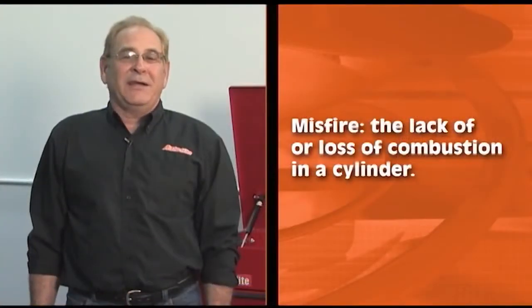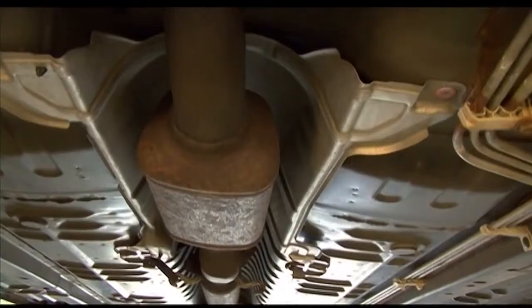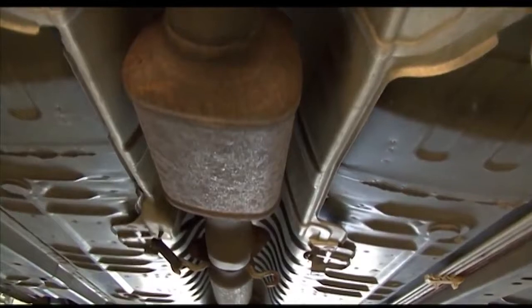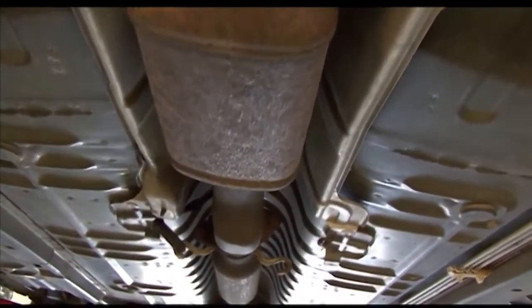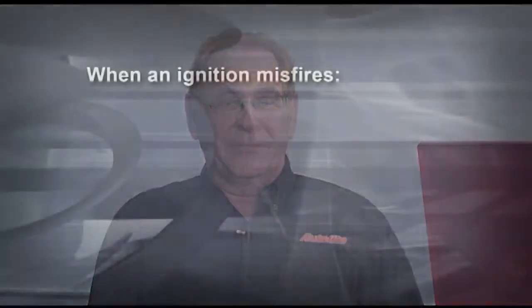A misfire is defined as the lack of or loss of combustion in a cylinder. When an ignition misfire occurs, raw fuel and excess oxygen are dumped into the exhaust system and catalytic converter. The converter runs very hot, causing the fuel to burn inside the converter rather than in the combustion chamber. The converter temperature can rise to a dangerous level and elevate hydrocarbon emissions output. The situation goes downhill from there.